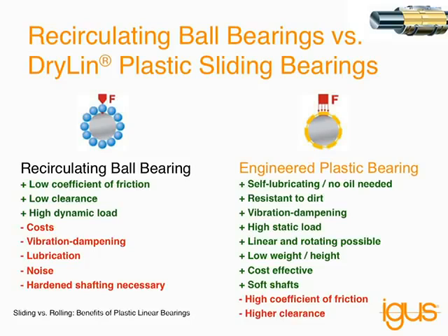This slide highlights the main benefits of each part, which are in green, and the main problems with each part in red. So you see ball bearings, because of their low coefficient of friction, enable applications that are hand powered to be moved easier. They require smaller drive forces. They also enable higher cantilevered loads.